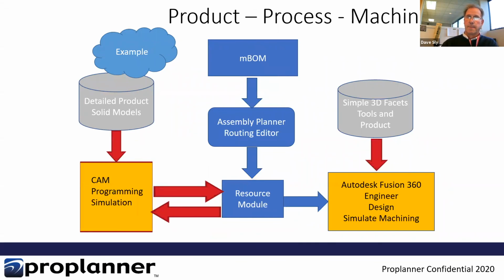Product, process, machine. So now what I'm looking at is what's tooling required? What tasks am I asking the machine to do? Is it within the capability of the resources that are being required? And I might link in CAM tools. And in fact, in some cases, we're actually taking basically NC code files or tool set ID files for machine tools as part of the process task description and publishing them to the resources. But of course, those resources have to be in those stations that those tasks are now currently assigned to. So we can publish those out to the equipment to do validation and verification.